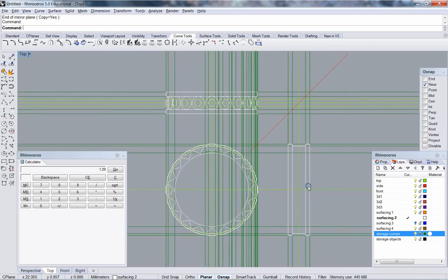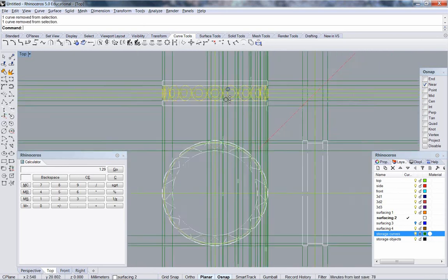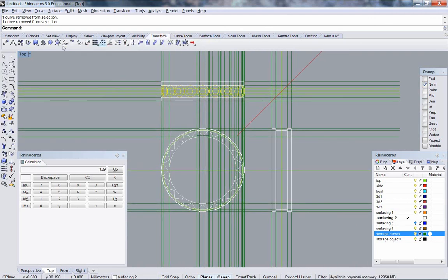Okay. But you do know that in a CAD program, we can just select those stones. We don't want the rims. We already have the rims. And we can do a rotation. Center of rotation, just like in the scale, it's very important. We want this to rotate around the center of this ring.